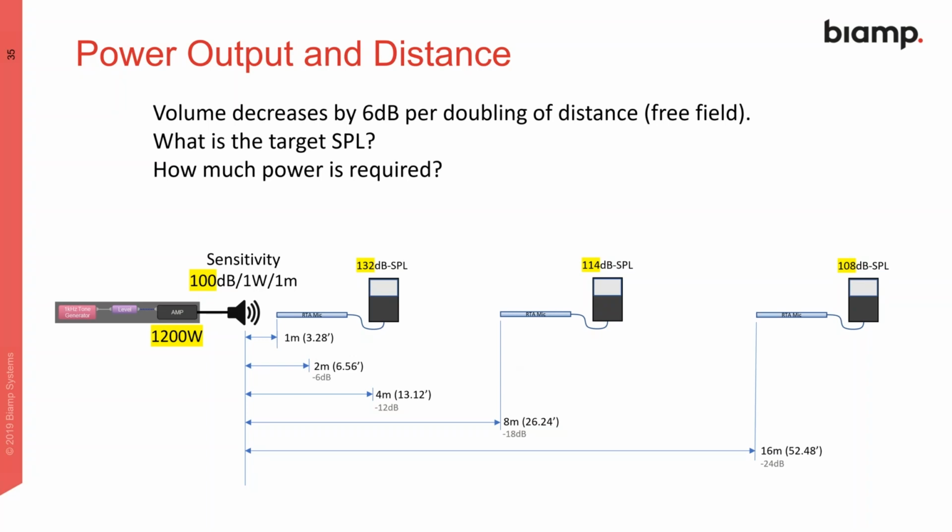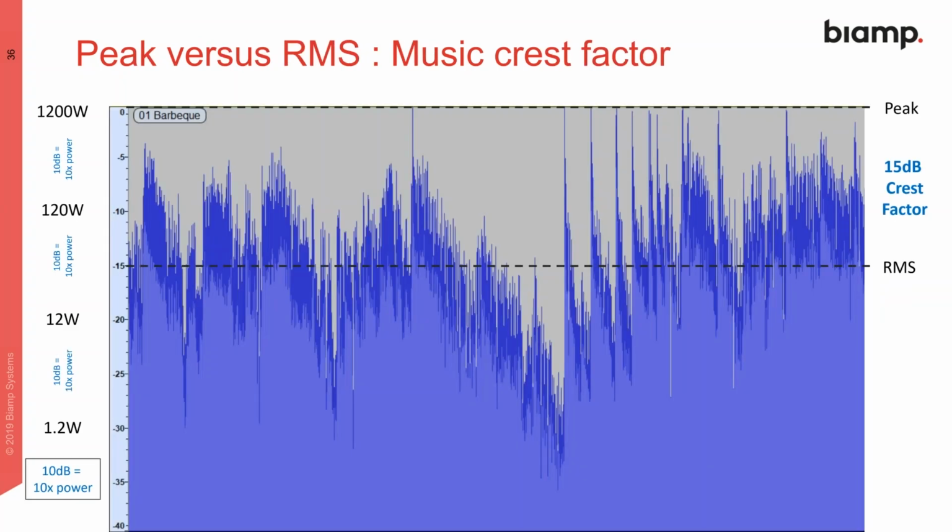All right, we're going to take a look at crest factors in program material now. I just grabbed a couple of files in Audacity and sampled them. What we're looking at here is a clip, just a generic song. At the top of the scale, we've got 0 dBu or 0 dBFS. So that is our peak. That's the normalized playout. It's probably within 1/10 of a dB or so of clipping for playout on Apple iTunes or whatever it is.